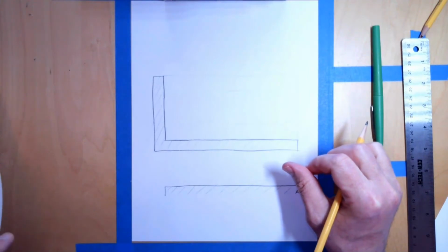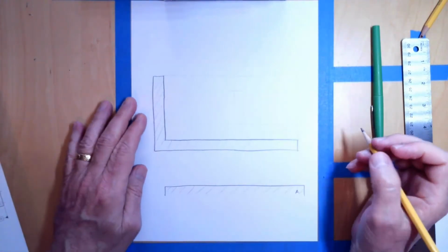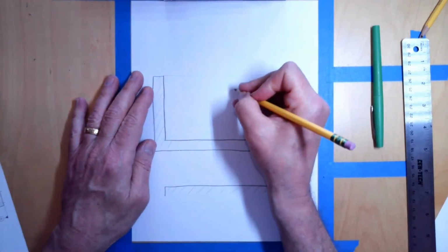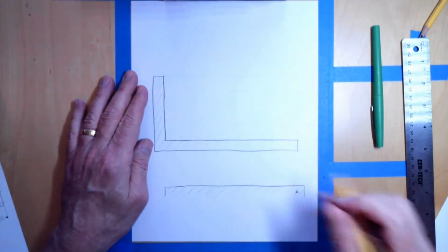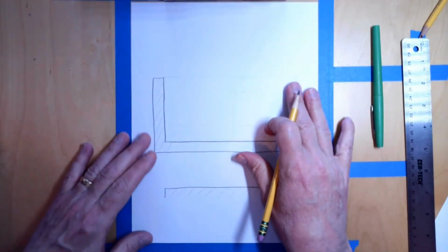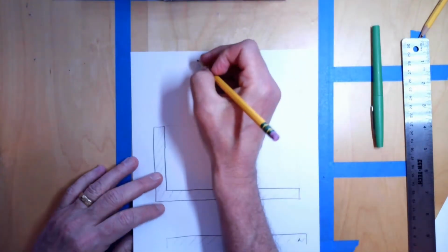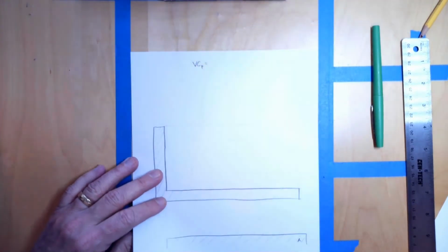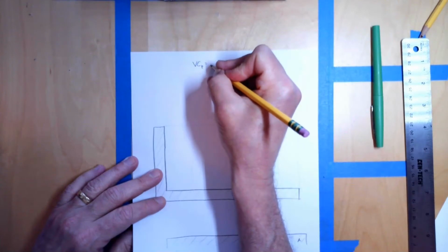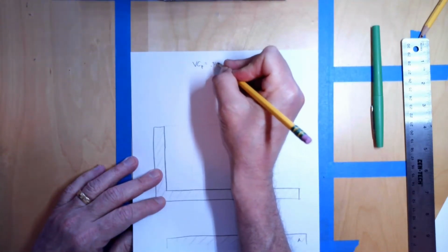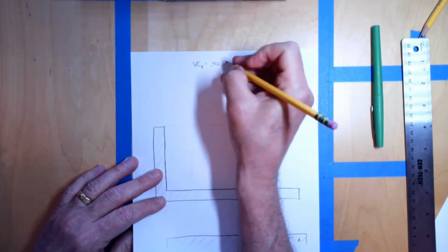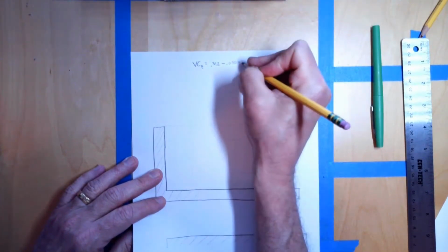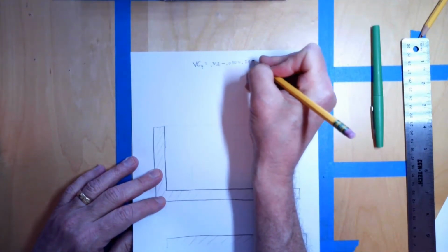Now for the pattern locating tolerance zones, okay, I'm going to have 3 pins, and the 3 pins, let's get the calculation for the size of the pins. So the pins for the virtual condition for the pattern locating tolerance zones are going to be the size of the hole at MMC, which is .312, minus the tolerance at MMC, which is .030, equals 0.282.